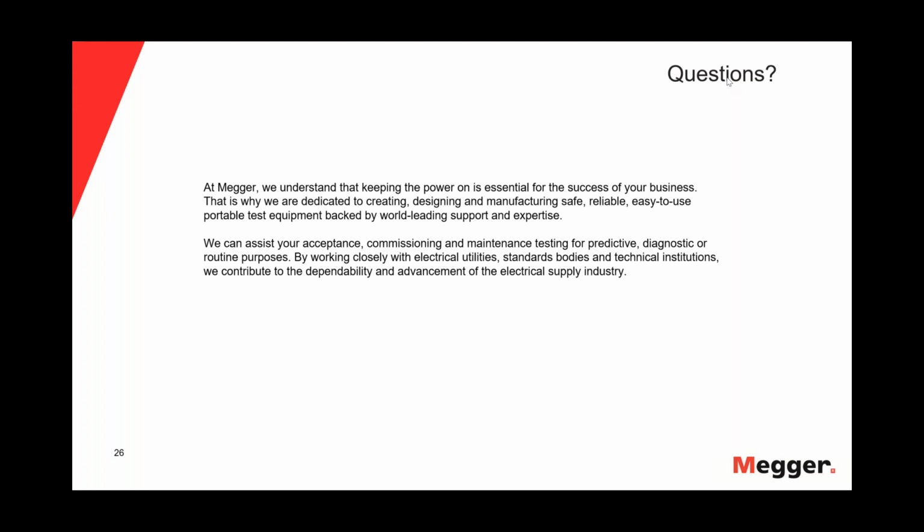And that has to do with the fact that when the cables are installed, they're not actually treated identical. So one cable could get some damage that the other two phases don't get. So when you have one phase that sticks out, that is much higher in, in this case, tan delta, that's what we talk about here, then you would have to see what it can mean.